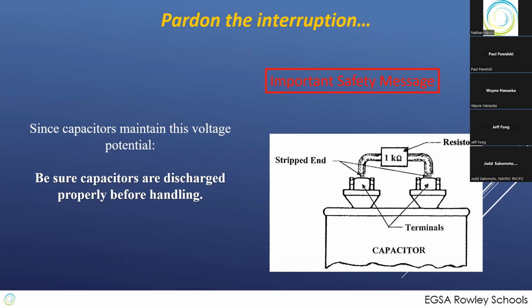If one of your technicians is doing it with a screwdriver, encourage him to use a different method. It's better than nothing, but it is much better to do a slow, controlled discharge of this. Always assume every capacitor you run onto still has a charge until you prove otherwise.